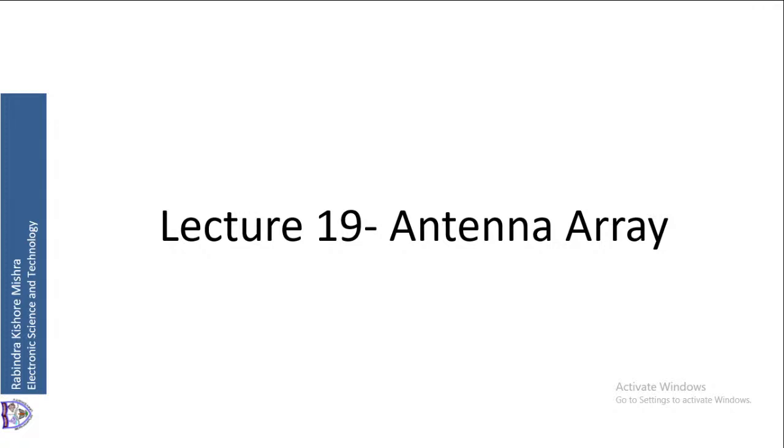And in fact, we will see that depending on the phase, the orientation of the main beam will also be controlled. So using more than one antenna, we can control the orientation of the main beam, the orientation of the null, and we can add power. This is the function of an array. That is why we are going to discuss antenna arrays, and these are the importance of antenna arrays.